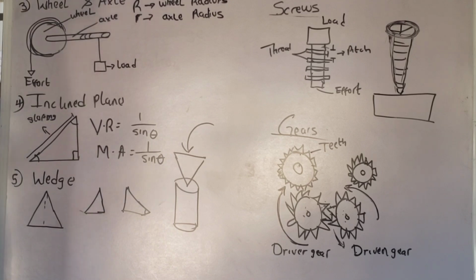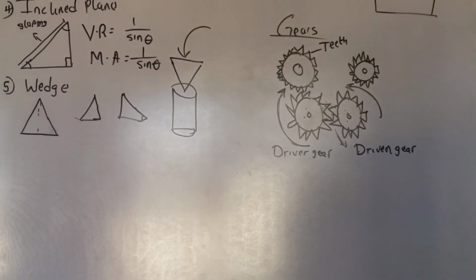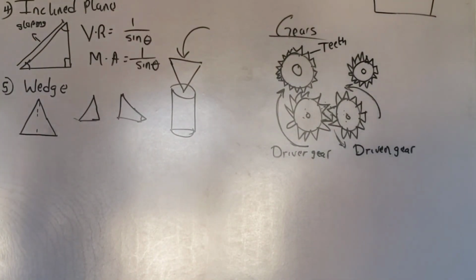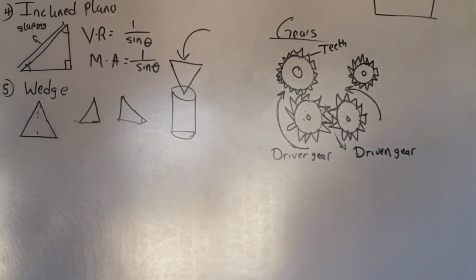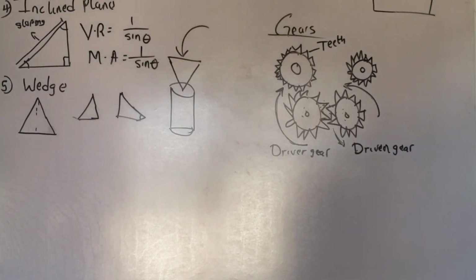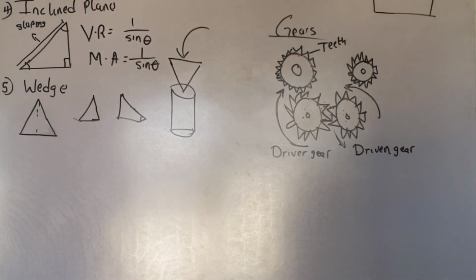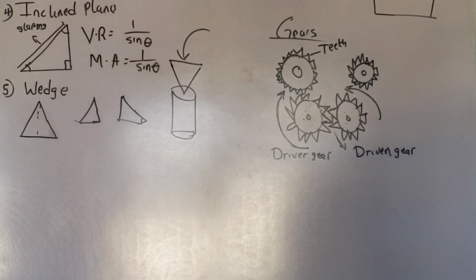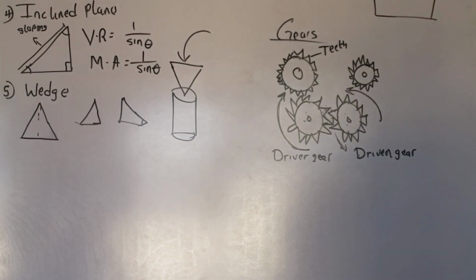So now, how do we use gears to increase speed and how do we use gears to decrease speed? That's what I want to explain now. To use gears to increase speed, the driver gear must be bigger than the driven gear.